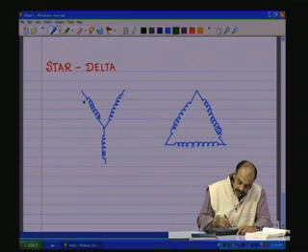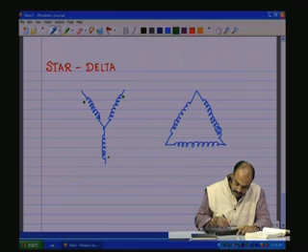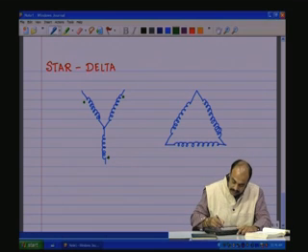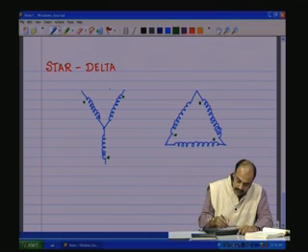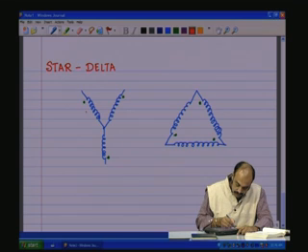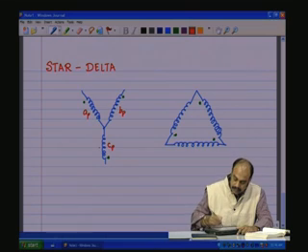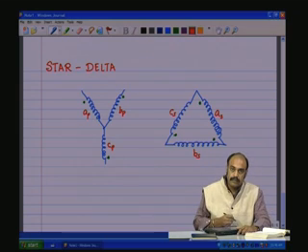Never forget to indicate the dot polarities in the three phase transformers in sequence. So, let us say this is the AP coil, the BP coil and the CP coil, and this is the AS coil, the BS secondary side coil and the CS coil.